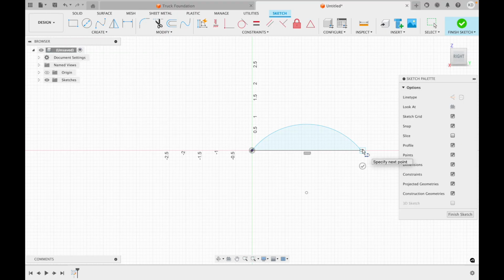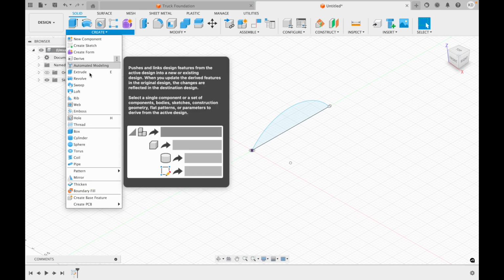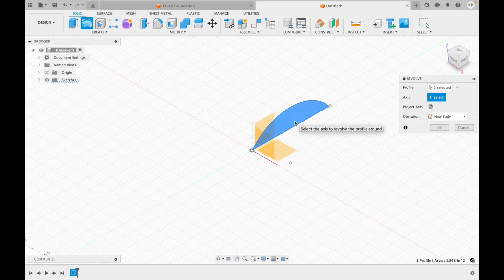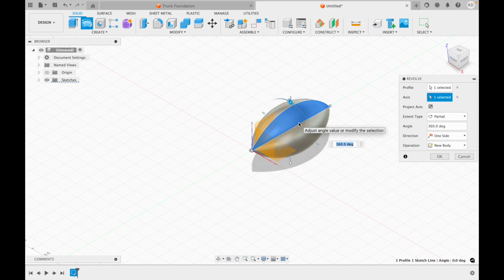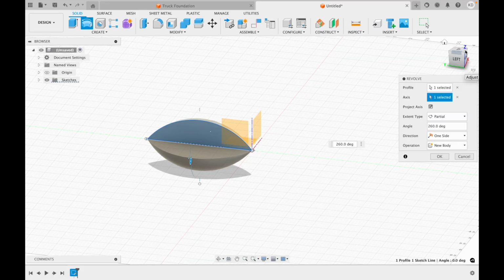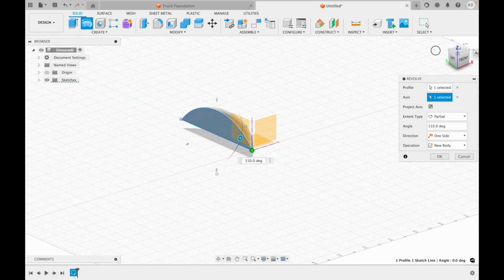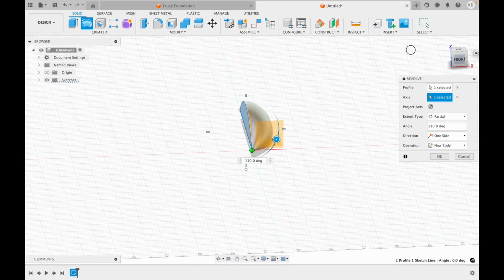And in that arc, we're going to close a line. And yeah, the new function that we are going to be using is the revolve function. Basically, it just revolves around whatever axis you want it to revolve around. And you can either make it closed and make it look like a football if you do the arc shape that I'm talking about, or you can have it be open and make it revolve a certain length. And essentially, it's just a really cool thing to use if you want a specific geometry or something else.